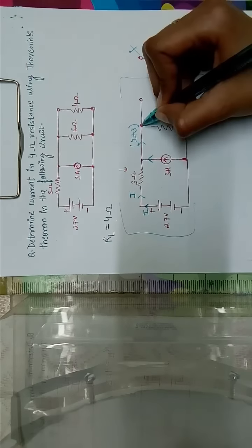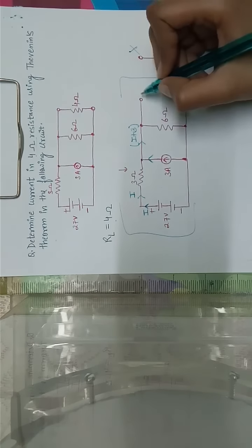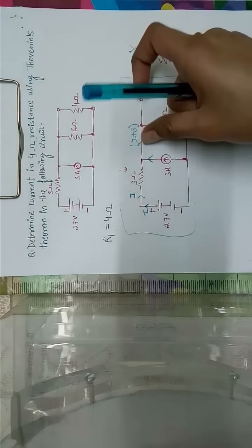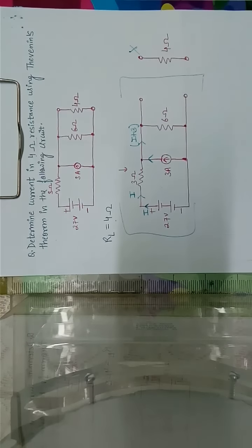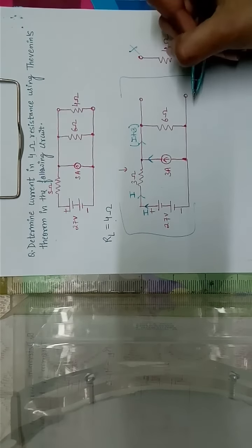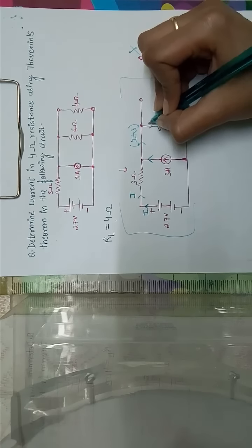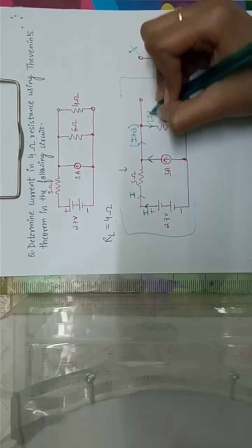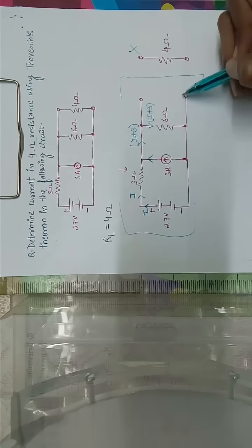Now the important thing over here that you need to see is that because this particular section of this circuit does not have a resistance involved and it's an open circuit, which means that no current flows through it, the current on a whole I plus 3 flows directly through this 6 ohm resistance and no current flows through this.